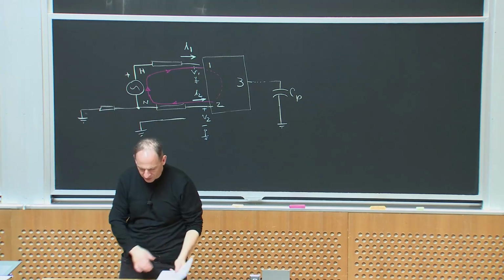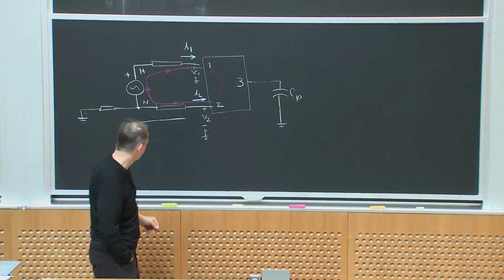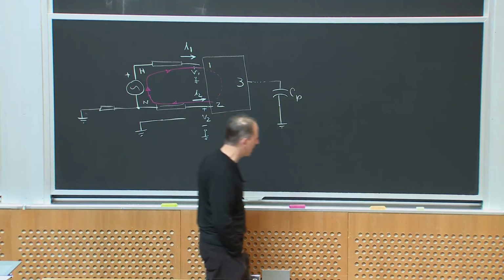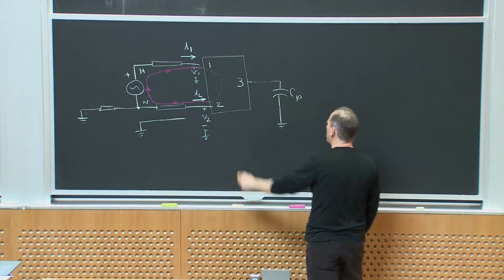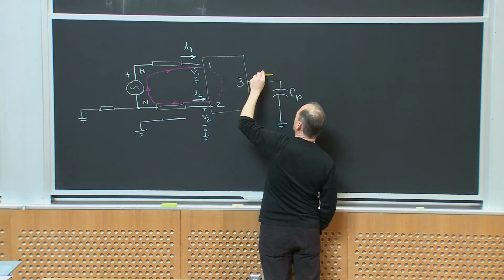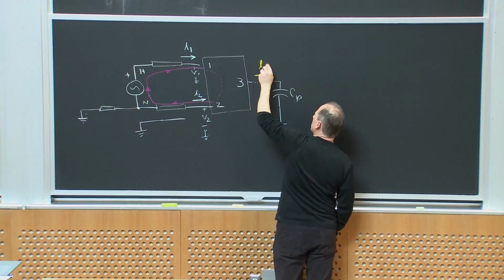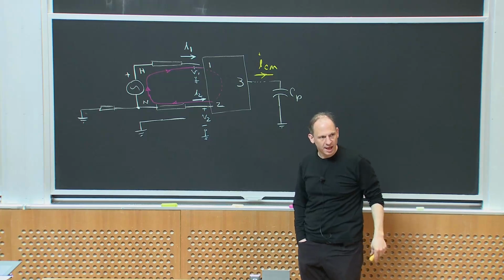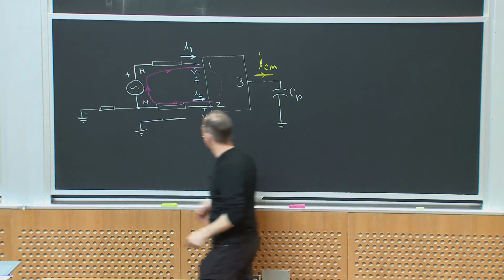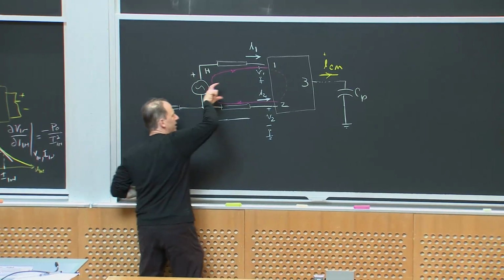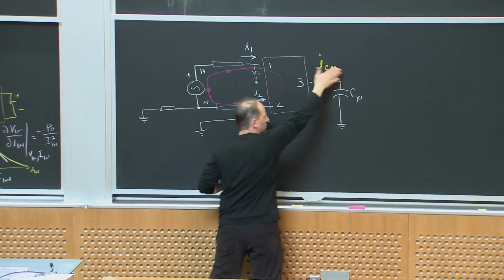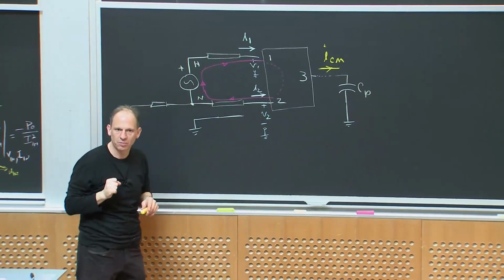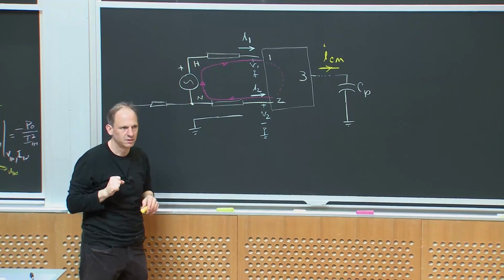If the other path does exist, we get what we would call a common mode signal that I'm going to call ICM, the common mode current. Common mode because I think of it as coming through the two leads together into the device and then out through the device through some third path. Does that make sense to everybody?